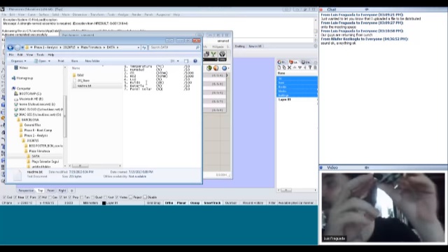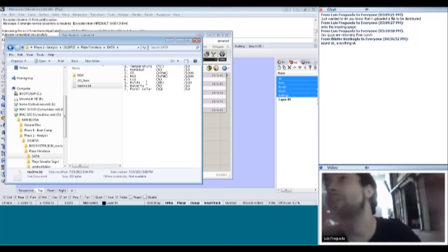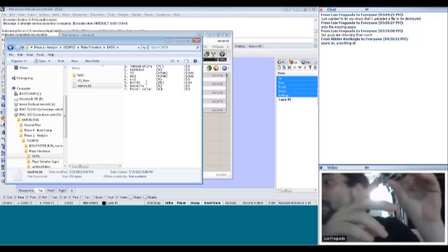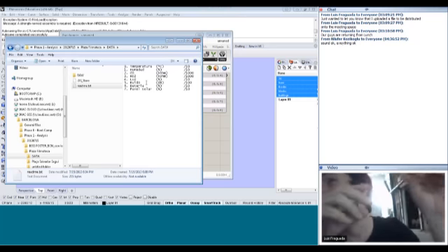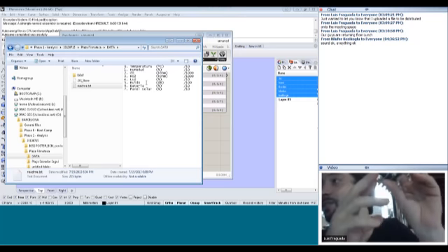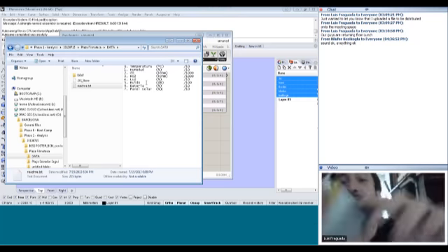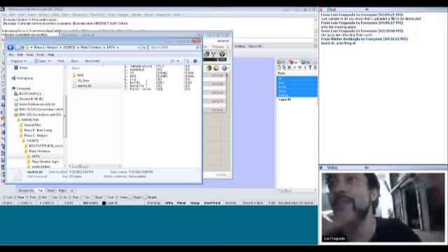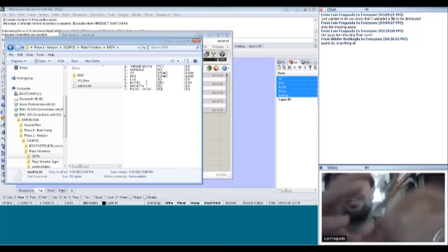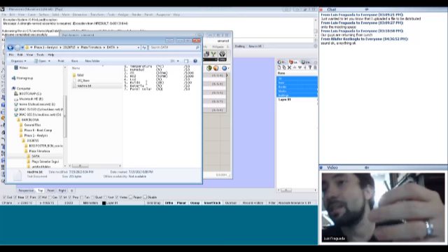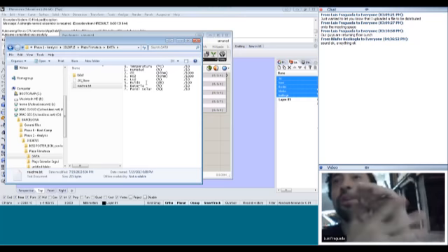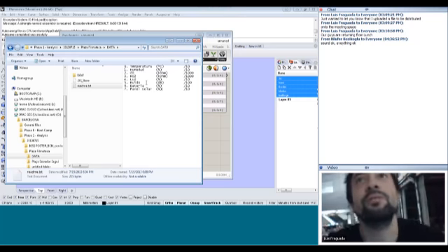How many are carbon monoxide? That's a really complicated thing to get back, especially with these low-cost sensors. There are very expensive sensors, in the hundreds of thousands of euros, that eventually give us really good precision and very accurate data.